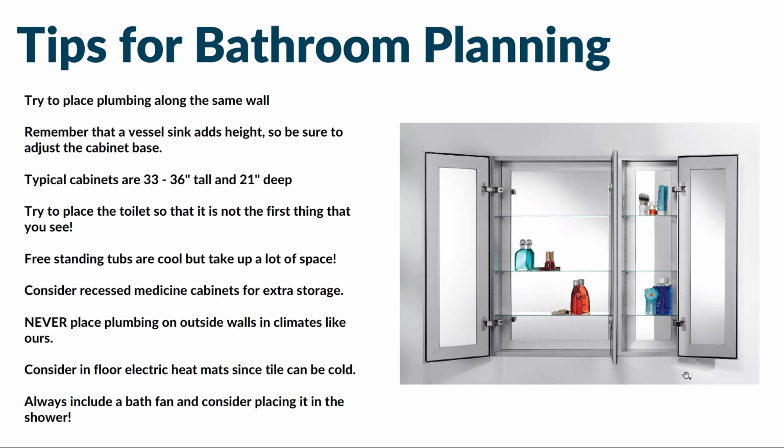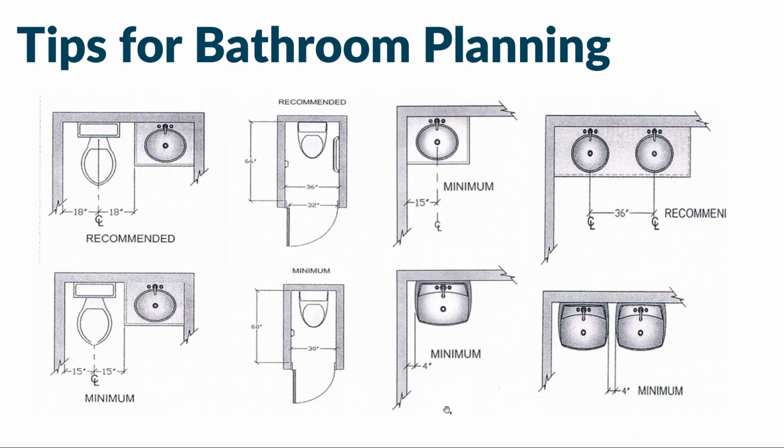You might consider doing heated mats or heated floors because the tile can be very cold, again, especially in those colder months. And always, always include a bath fan and consider putting it actually above the shower if possible to get the steam and moisture out of the bathroom to prevent mold and mildew and those types of things. So, just looking at some layouts for bathroom planning.